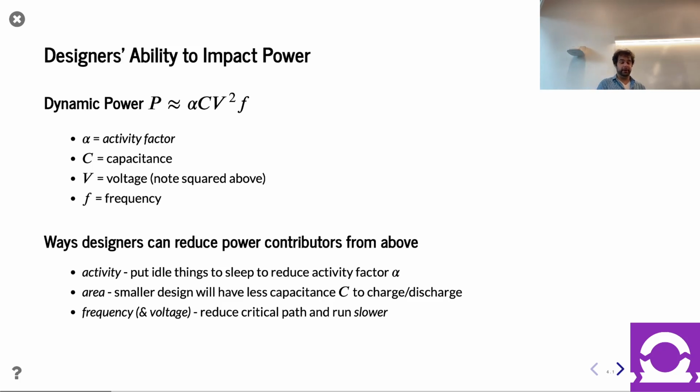The reason is, if we think about all the various paths in a big circuit, a lot of them aren't really being toggled. They just have some value and aren't active right now. The fact they aren't switching is an important thing for us to take advantage of to save energy. And guess what? It does naturally, from a dynamic power point of view. If you switch a circuit less often, it's going to burn less power.